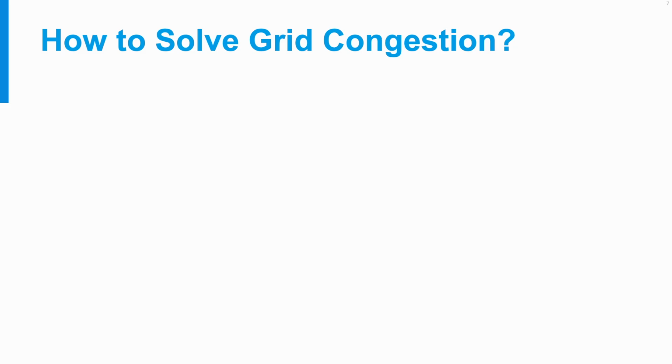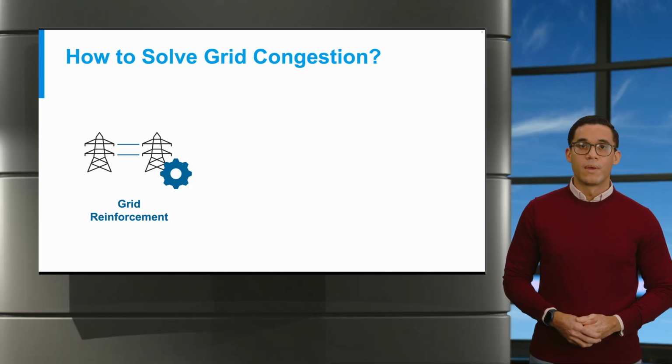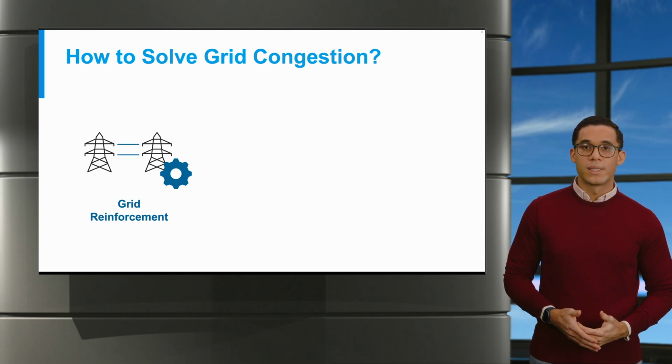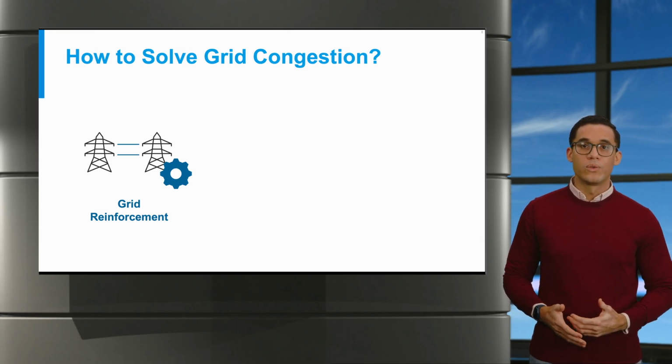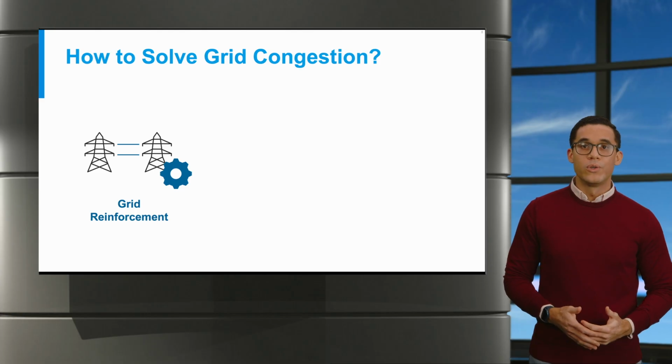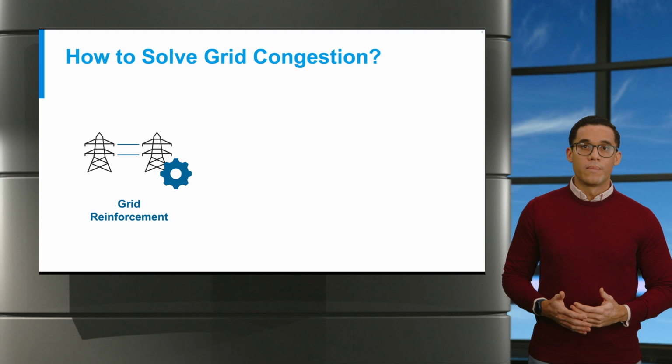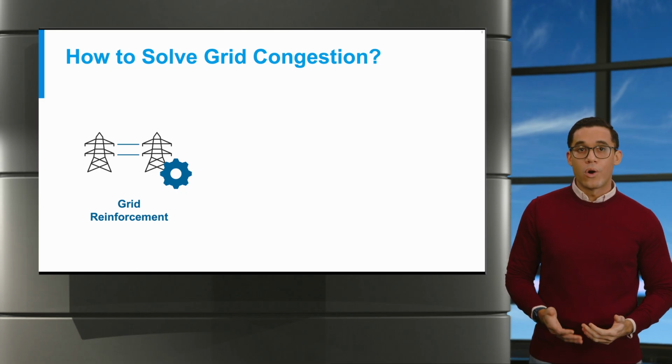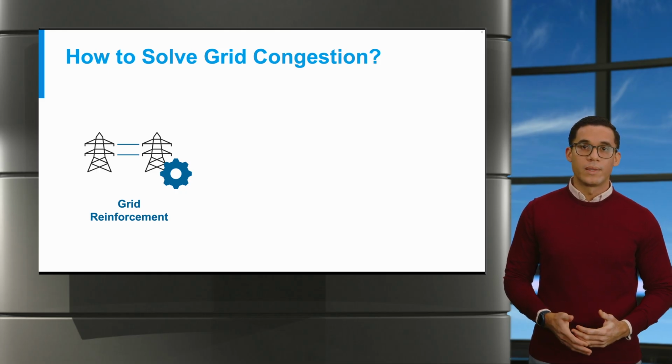How do we solve it? The first is grid reinforcement, building more capacity. This is essential because it solves fundamental shortages and it is the most resilient way to reduce congestion. But reinforcement alone won't be enough for all future use cases. With large amounts of new generation connected in lower grid levels, and with more all-on, all-off demand patterns from electrification, it is not realistic that we can build reinforcement fast enough or affordably enough to always guarantee unlimited capacity everywhere.